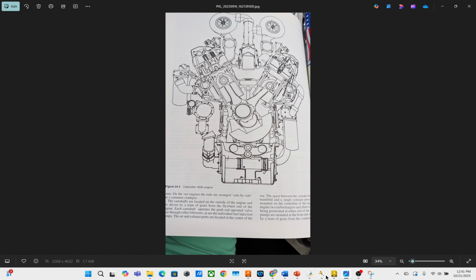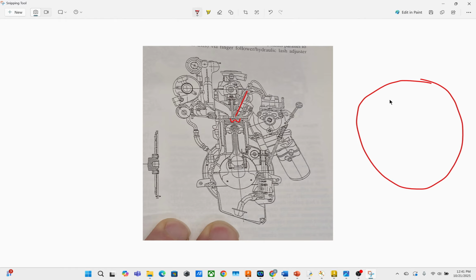So if I'm going to go ahead and do this, I might as well just make the cylinder have 4 valves and put the injector right in the center. Not only do I get way more curtain area of each of the valves so that there's better flow for intake and exhaust, but I also now have room in the center to put the injector. So that's where I'm at.